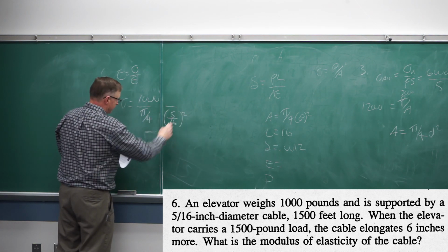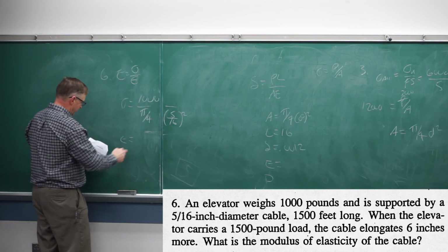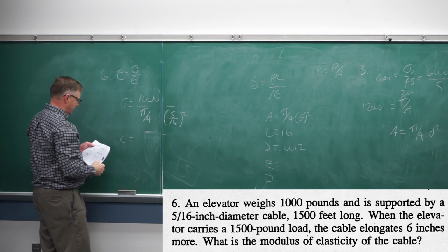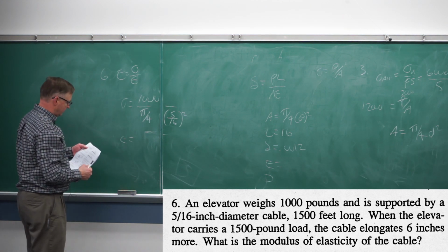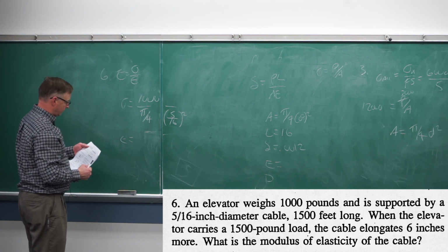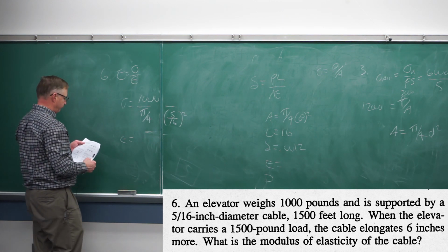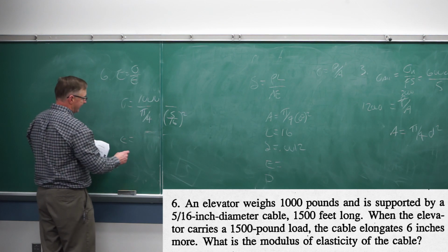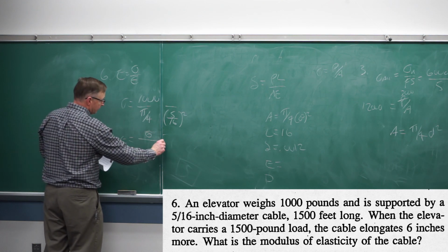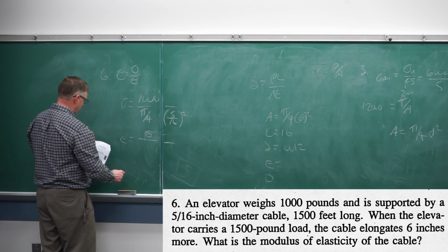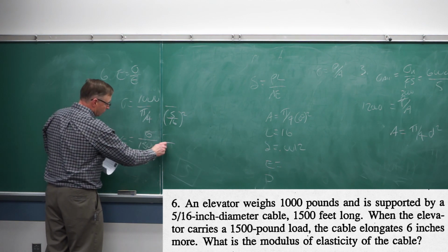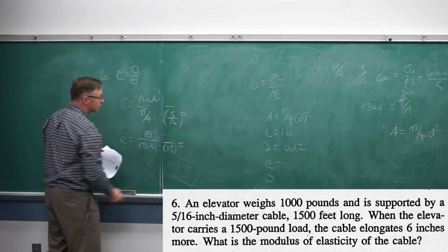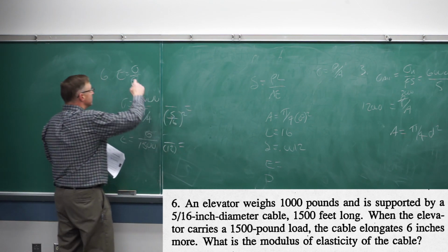And strain, it elongates 6 inches over 1,500 feet. So it elongates 6 inches, but to keep those units consistent, you're going to need that 1,500 feet multiplied by 12. So that's going to give you strain, and the modulus is going to be just stress divided by the strain.